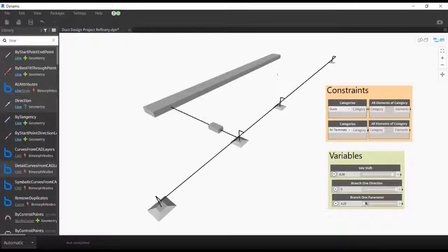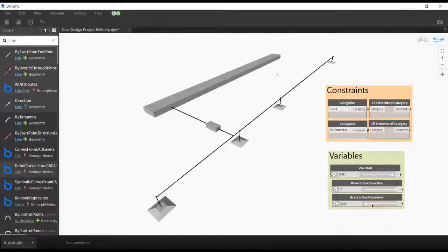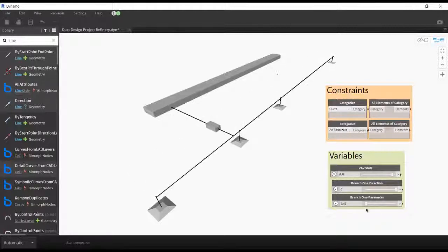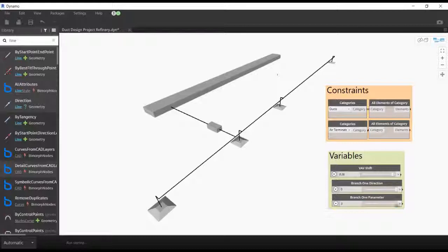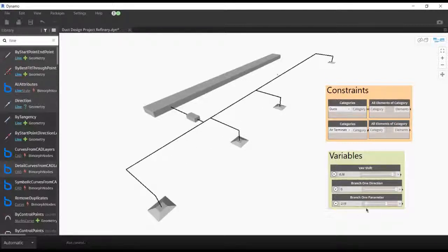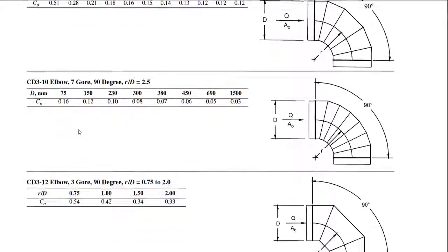But to be able to find the best, we want to get a cost function or rank them somehow, a score, but the terminology is cost function. This could be of the energy, the cost to install it. In our case, our goal, kind of related to energy, is we want to minimize pressure drop. So in that problem, there's a sub-problem, and that's finding the coefficient for duct fittings to be able to calculate the pressure drop, and that's what we're going to solve today.